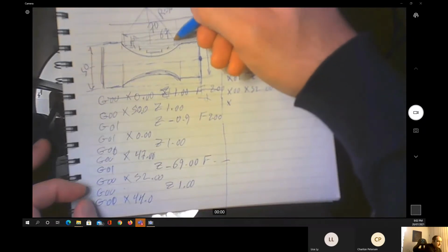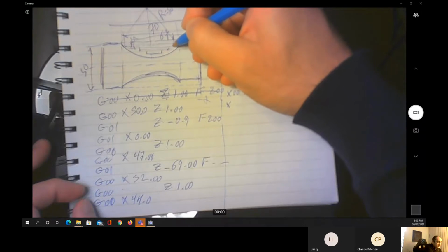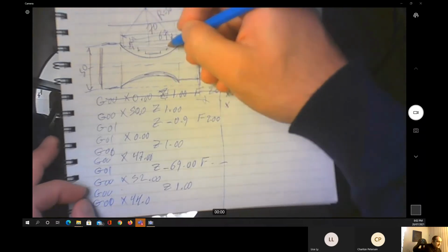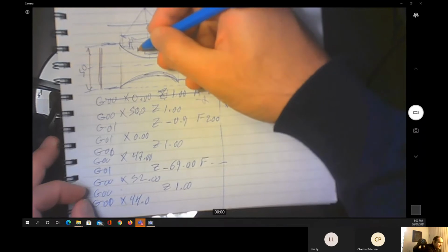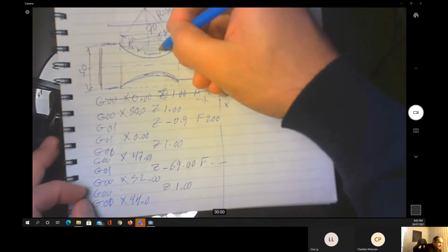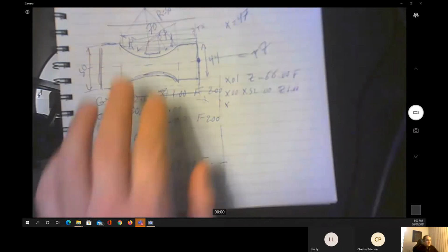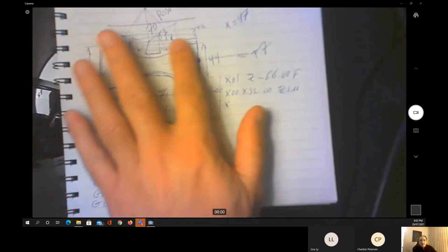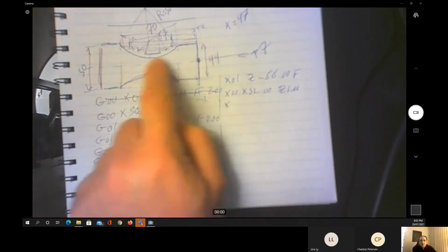I only need to come back to this position. So I'm going to be here. Then I'm going to insert the cutting tool in this position, going in another straight line, then going up to that position, going down, cut another line, going up to that position and cutting this part and going up. By that, I clean all this area and I'm ready to cut the final cut we are going to have here.